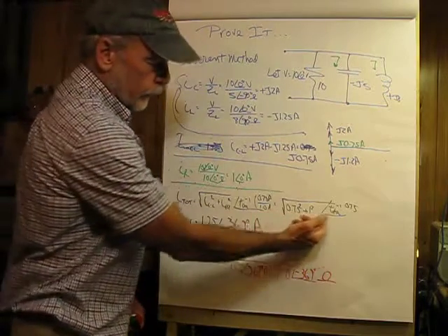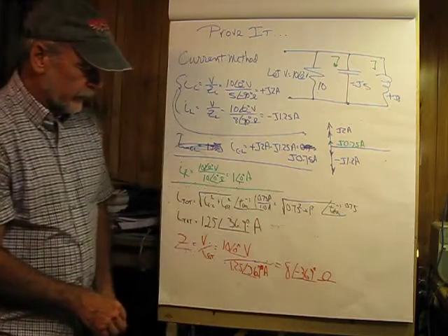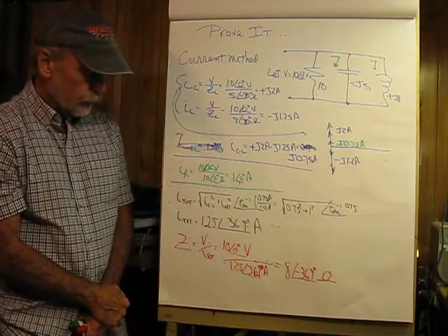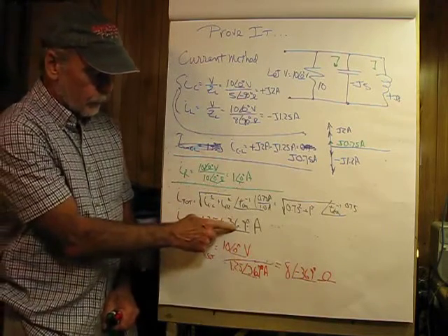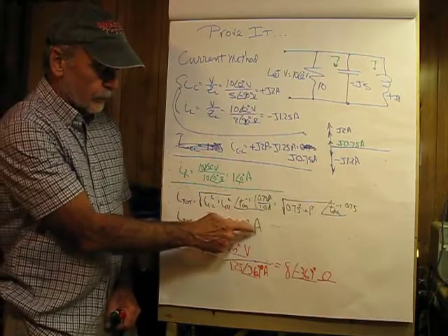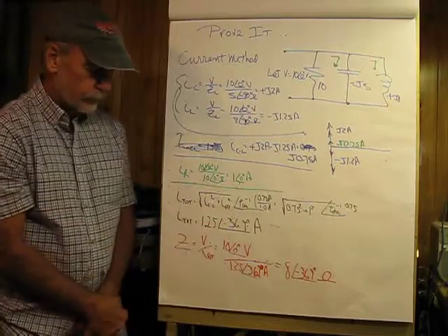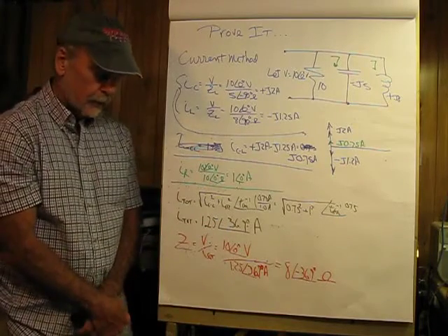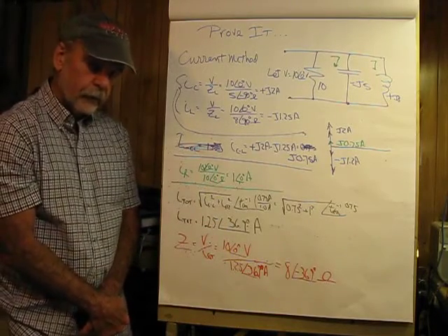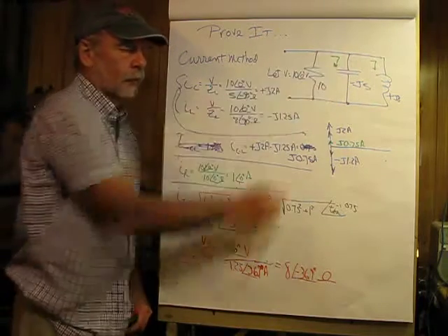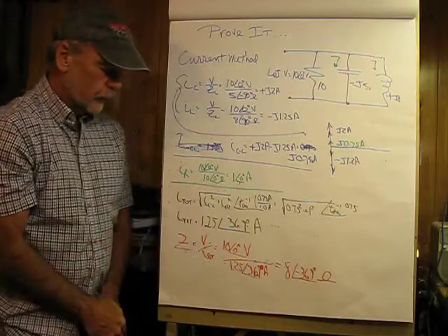So there we see it all expanded, and the total current comes out to be 1.25 at 36.9 degrees amperes. I like the sign on this. Plus indicates that it's a leading current from a capacitor. We would expect that again because more current is flowing through the capacitor than through the inductor.